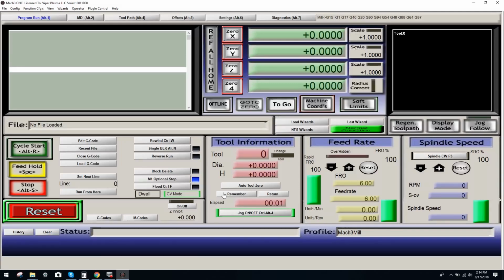But if you're using the machine as a true CNC, 9 out of 10 times soft limits and offsets are by far more effective than using any type of physical switch, especially when it comes to safety, because of all these challenges that people have put towards me, no one can argue the fact that a physical switch will fail. No one can argue when that switch will fail. We don't know. And when it does fail, your machine's at risk and your machine will crash inevitably. So think about it in terms like that. I think that really enlightens you to why I've always chosen to use the software.